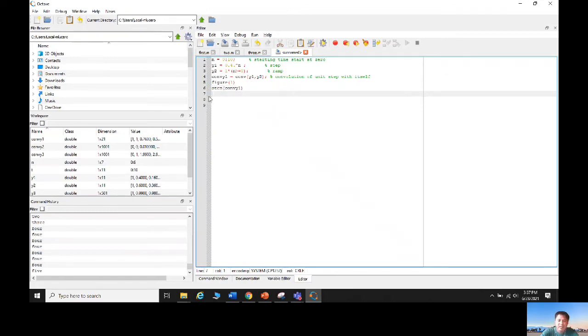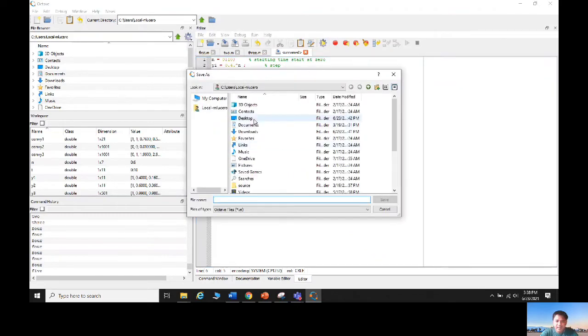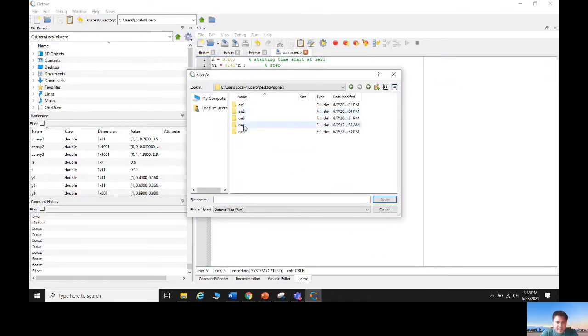So this axis is no longer needed anymore. So we use stem here because if you remember in my last video, if we are dealing with discrete signals, we will be using stem instead of plot. So we can try this one. So let me first save this.